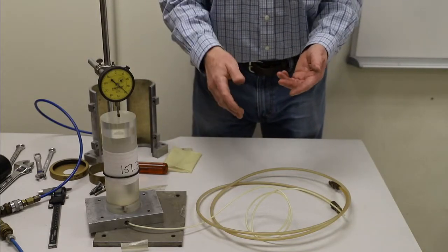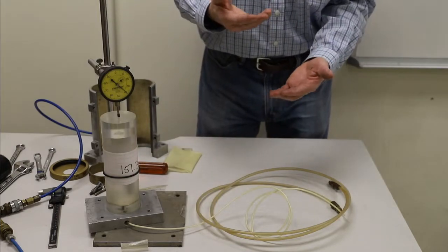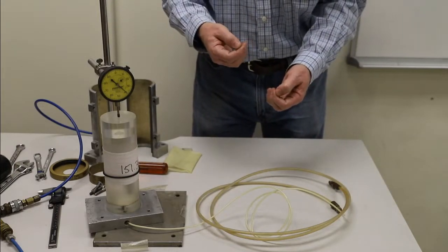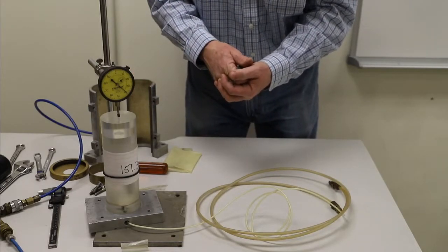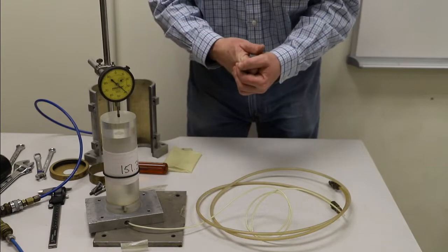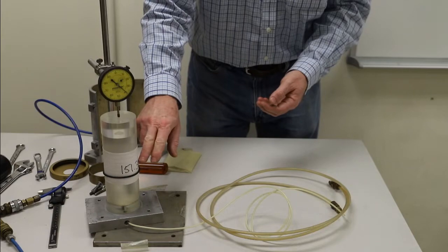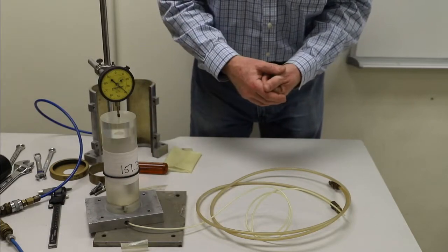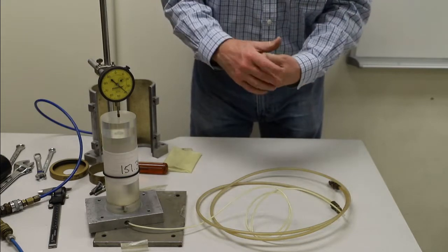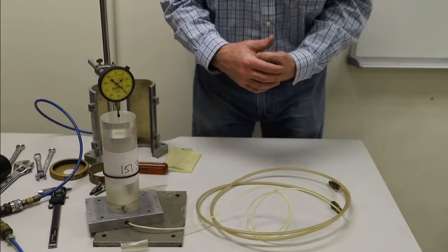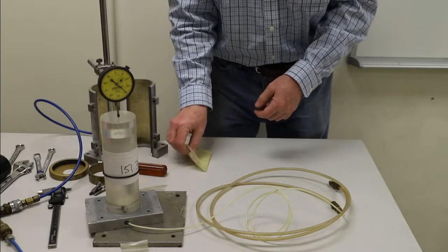What we're going to do later, after we've replaced the cylinder with our sand specimen that's about the same height, we can put the whole system back under the dial gauge, take another reading, and the difference in those readings will tell us the difference in height between this known standard and our specimen. This gives us a lot more precision than we'd have if we just held up a ruler or calipers or something like that on the system. So that's one of the early reference readings we would take.